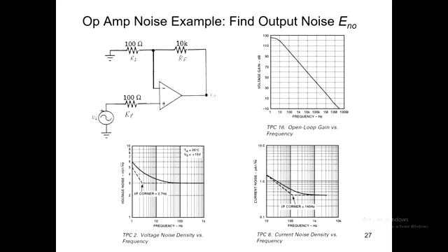Yes. So if we draw a closed loop, one on feedback factor line here, it will intersect over there. That will be the bandwidth, correct? Because after we get to this point, the ideal closed loop gain can't be achieved anymore, so it will follow that line. So this is the break point for closed loop gain.